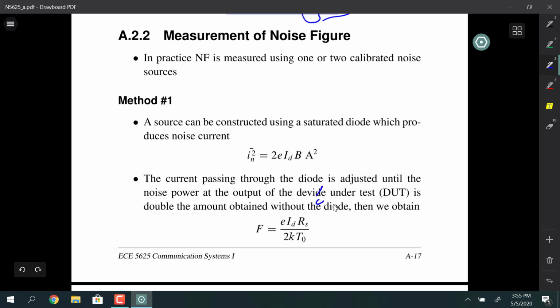Should be device. And on a project that I was on, I had to build a low noise preamp. This was the interface to a photomultiplier tube and the front end of the optical comm system that I was responsible for on my very first assignment. And so I got exposed to that. After I built my preamp, I had to go get checked out to me the noise figure test set from the test lab. And then I had to do measurements on it and see how it was looking.